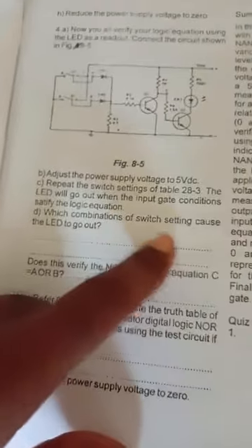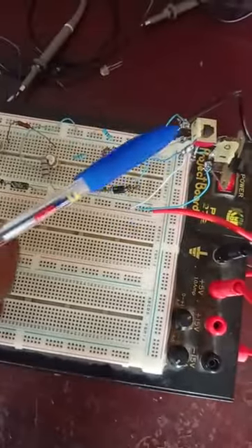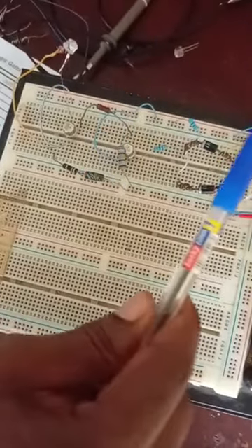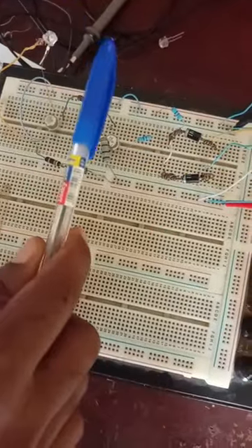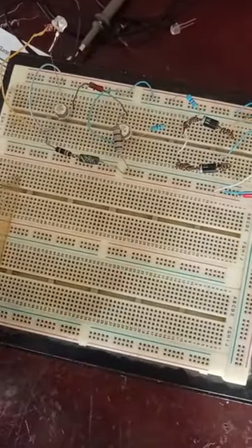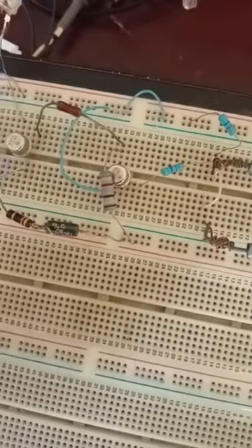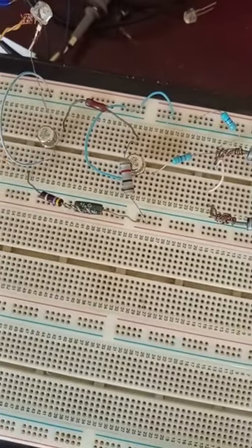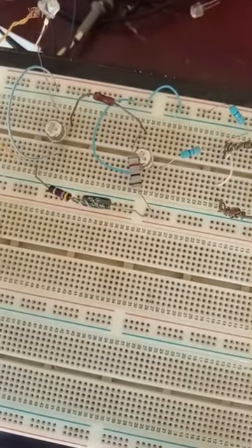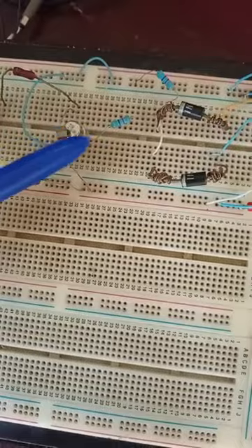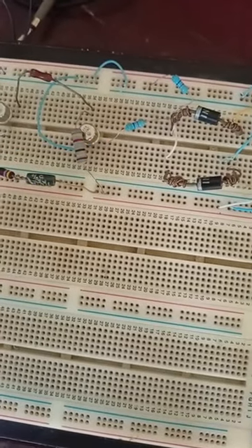So which combination setting caused the LED to go out? Let's now see. This is the circuit. We have switch 1, switch 2, the 2 diodes. Before, we had the cathode connected to the switch, but now we have the anode connected to the switch and the cathode connected to the base of the first transistor, second transistor, and then we have our switch outside here, the way we have it for the NAND gate. We just have to change. The only difference is that we reverse the operation of the diode, and then instead of having another diode there, we have a resistor there. So that's that about that.